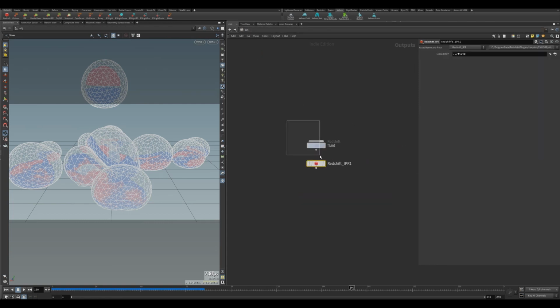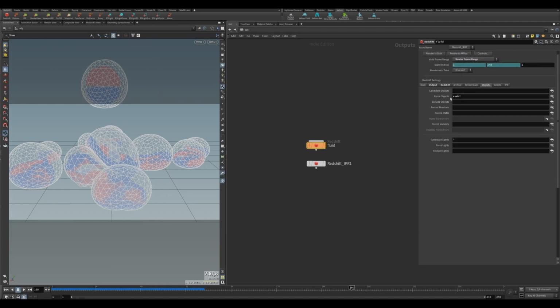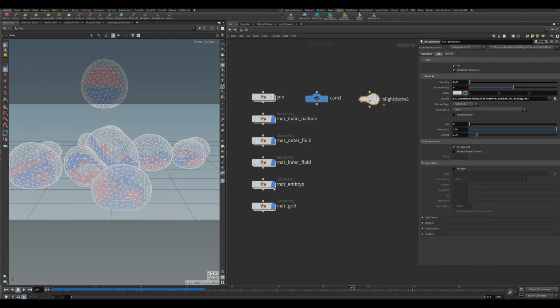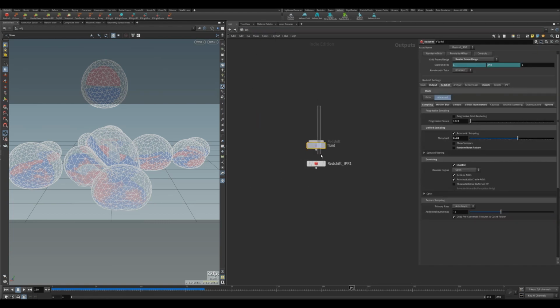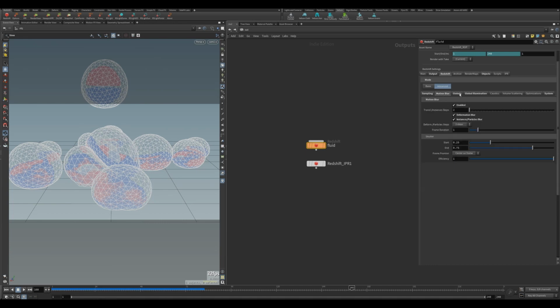Output. So there's the render ROP itself. Render ROP, again, no big deal. I just made sure that I forced the render of objects matching an asterisk, because if you notice here, all of these have a prefix called RNDR, and that's why. And I have a threshold of 0.02 because I didn't mind it having a little bit of noise. I was okay with it. It's usually 0.01. And denoising is enabled. And the motion blur,